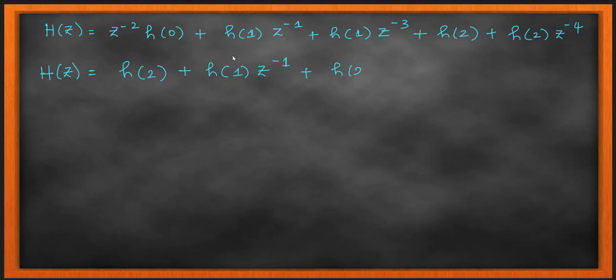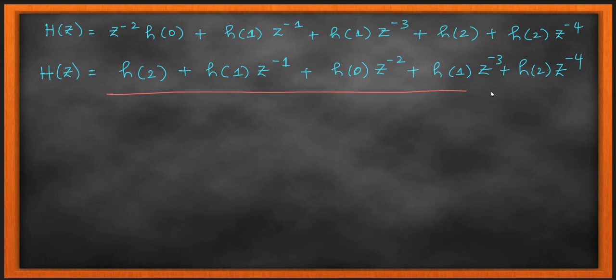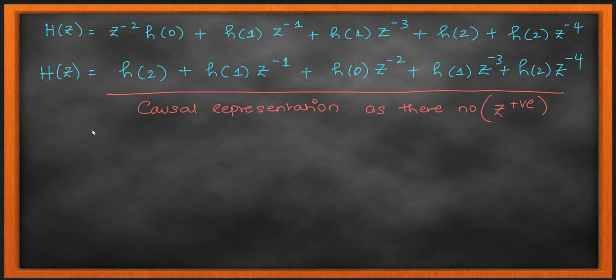See what we have done. We started with the Fourier series equation, because we are talking about FIR design using Fourier series. The first thing I did was make it finite. The second thing I did was induce symmetry, by taking z to the power of n plus z to the power of minus n. And the third thing is I removed the non-causality: I converted it from non-causal to causal form by multiplication with z to the power of minus (m minus 1)/2. And what is causality?